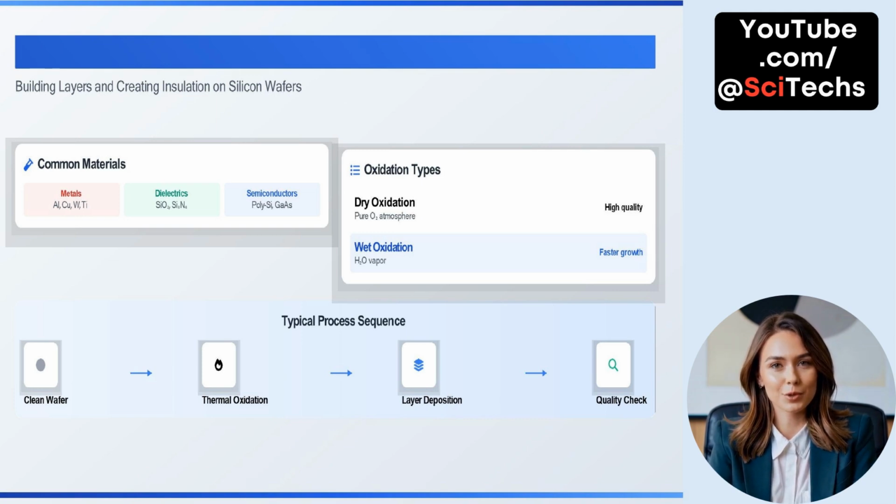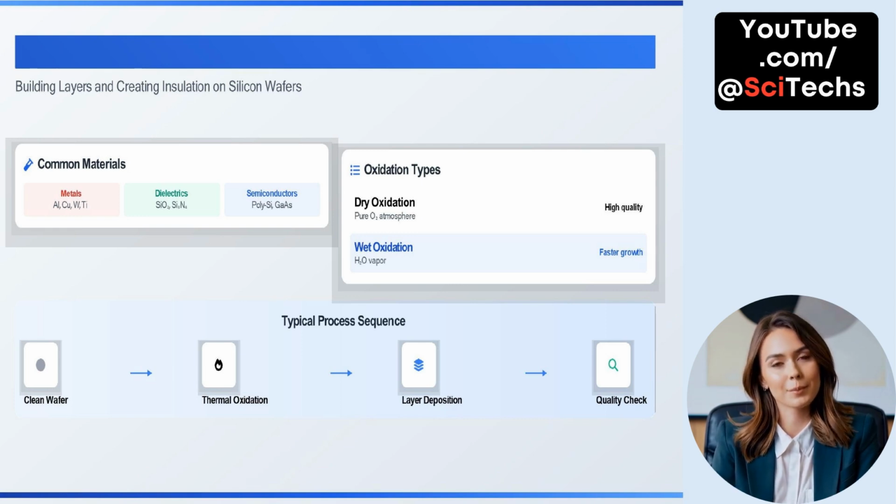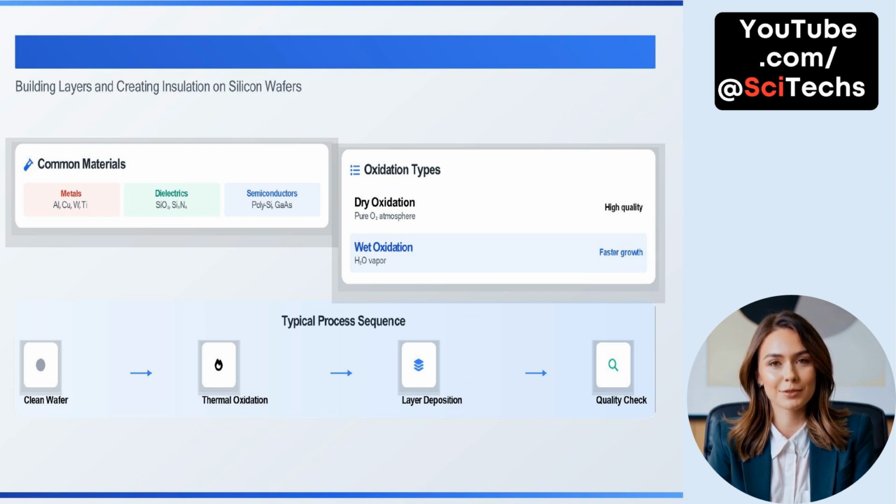Oxidation types play a key role in insulating layer formation. Dry oxidation, which uses a pure oxygen atmosphere, produces high-quality, dense oxide layers, though it grows slowly. Wet oxidation uses water vapor, H2O, and enables faster oxide growth, which is ideal for thicker layers where speed is a priority. The typical process sequence starts with a clean wafer, followed by thermal oxidation. After that, layer deposition occurs. The final step is a quality check to ensure that specifications and performance standards are met.